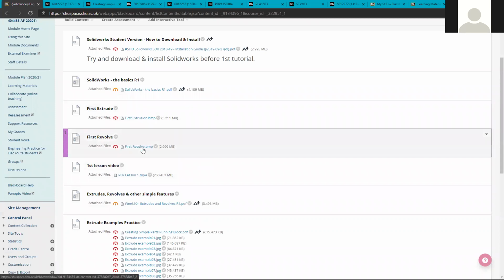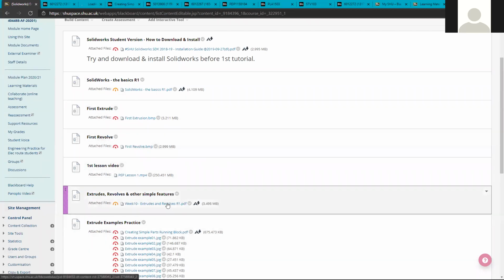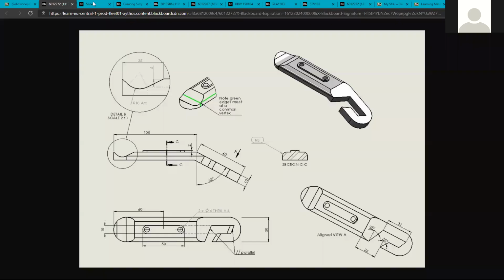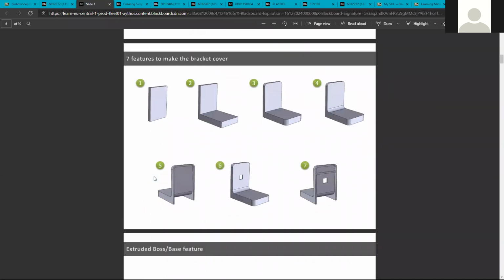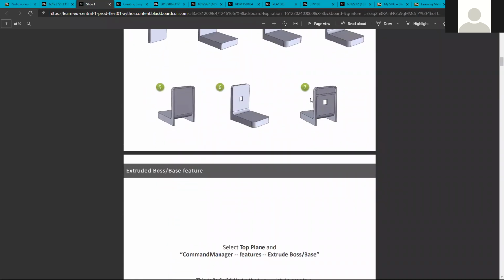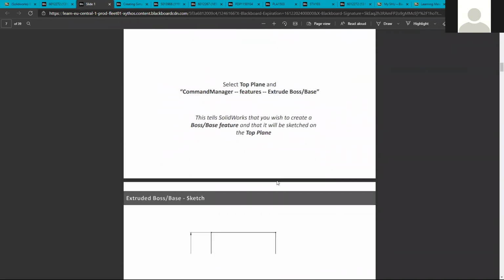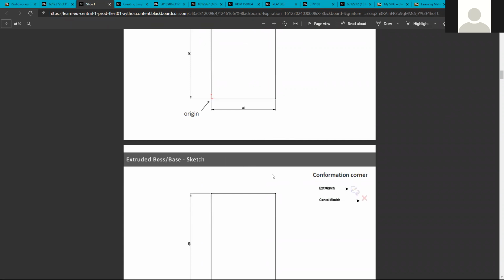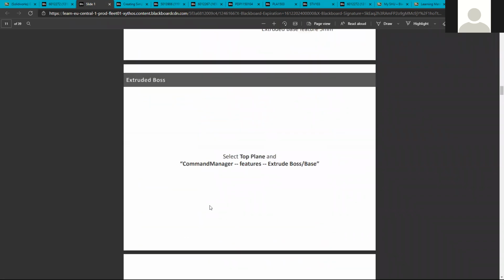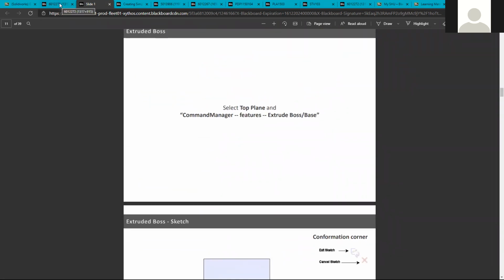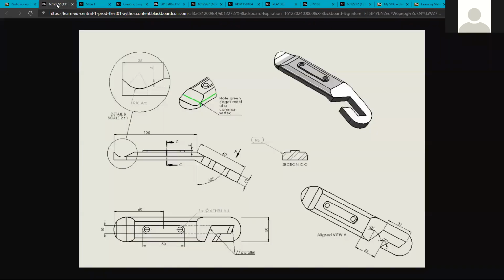We've done some basic extrusion and revolve work, I think, last week, and a little bit more practice at using those tools. We use the shell tool and a fillet tool there as well. So just getting our practice in terms of using the sketching mode and all the different options: blind depths, up to next, through all. So yeah, we've had a little practice at using some basic tools.